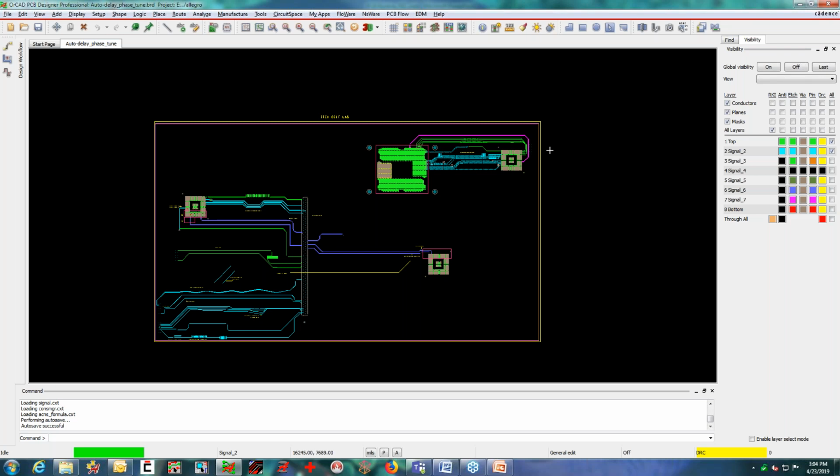And at the end, I can also review the waived report and make sure that I didn't waive something that shouldn't be in there. So that's the purpose of it. But to answer your question again, if you have a route keep out, it does look for any copper violation in that area, and that includes copper pours.